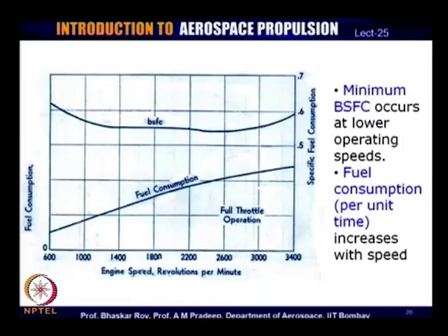We have also seen that higher the engine speed, higher the power production. So, there is always a balancing act that the operator has to find out between high power creation, which obviously has high fuel consumption. On the other hand, the BSFC also starts going up. So, if you keep an eye on the efficiency of the engine, then you would probably like to operate somewhere at slightly lower values of engine speed, and we have seen that at one of these lower values you also get a high torque.